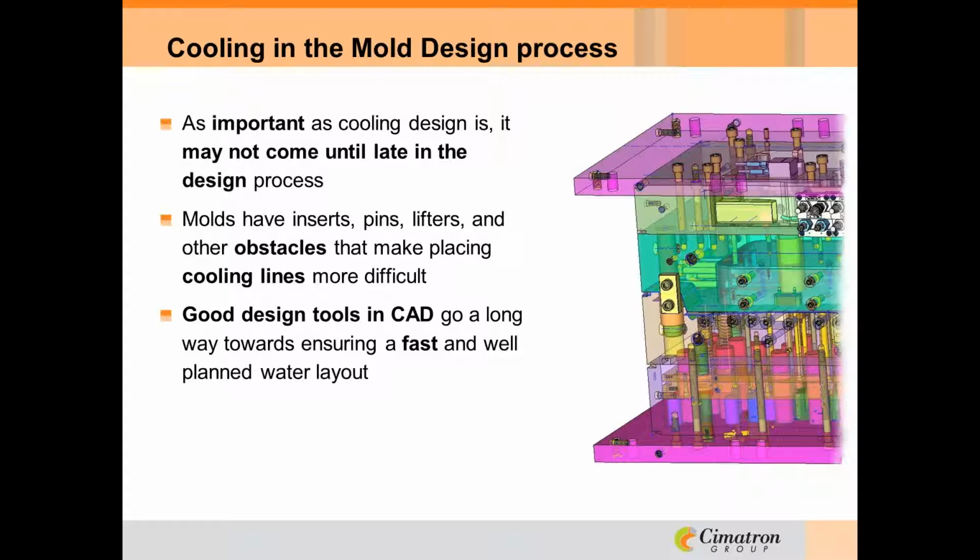To the mold designer, cooling is just one of the working systems in the mold. The shape of shutoff, the size and arrangement of cavities and slides, this is always the first concern. Then typically the gating of the part must be addressed next. Designing the cooling system generally comes near the end of the mold design process, out of necessity really.